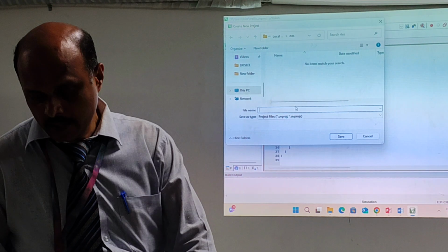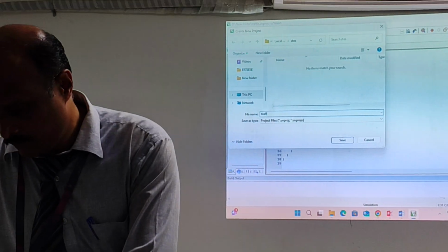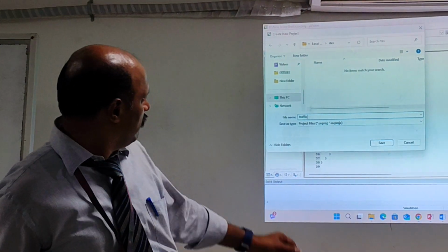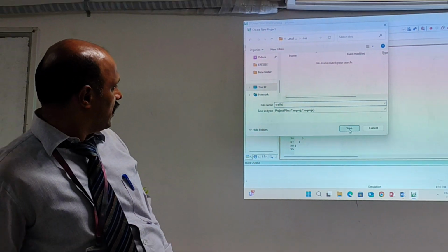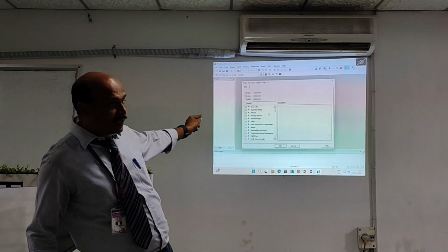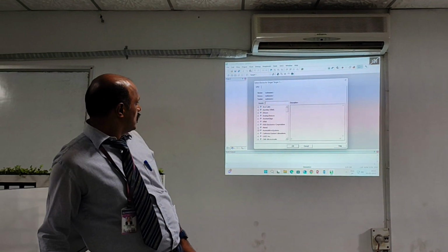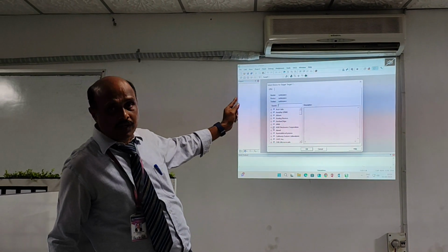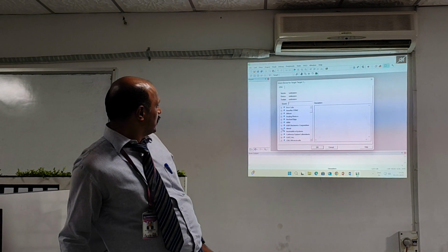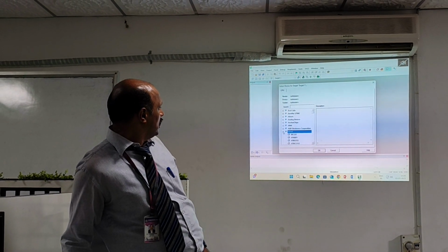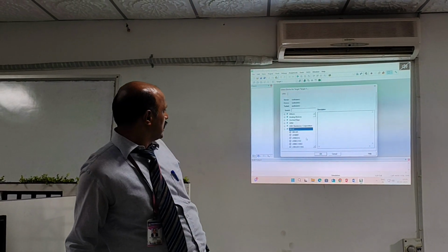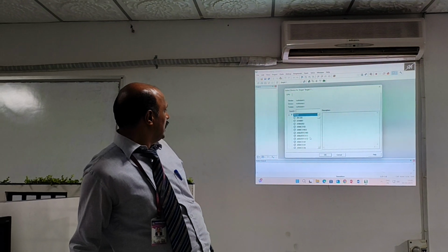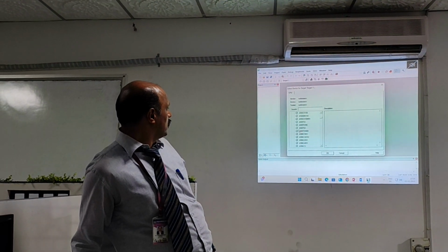I am going to give a file name also. For example, I am giving traffic light. When I click this, it asks to select the device for the target. So for that I have to select the device. Here I am explaining. I click ATMEL, and here I select AT89C51.